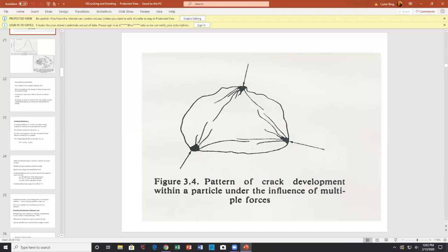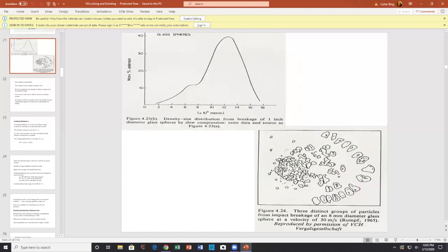That's counterintuitive. Dullness leads to more fines. Sharp edges lead to fewer fines. That's counterintuitive, but that's what actually occurs. Now, if you notice, we have three different particle sizes being produced. And if you throw it out on a sheet of paper, you have the fines here, perhaps the intermediate particles here, and the larger particles sitting out here.